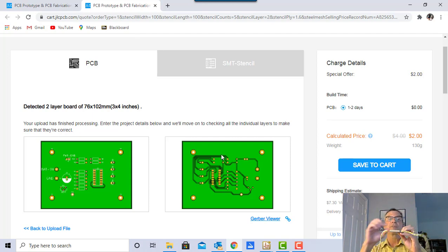If you go through Mark, you're going to get a board that looks like this. And you're going to have to solder the top and the bottom of your components. You're going to have to solder the top and the bottom of those vias that we put in here. And without solder mask, you may have some debugging headaches because you'll get solder bridges. But it's very common. Most students use our SDSU boards for their mini projects.